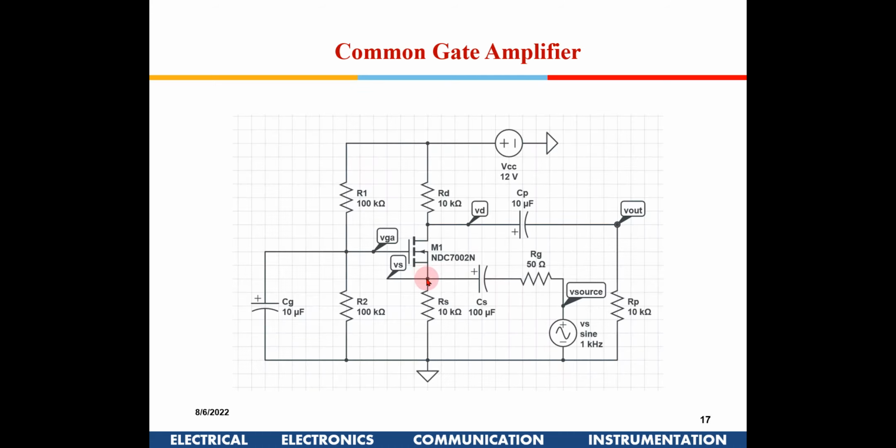Here, the signal is between the gate and the source voltage. Is there any voltage gain from this place to this place? There is no voltage gain. Voltage gain is between here and here. So the equivalent capacitance will come down. It will not get multiplied by the gain. Is it understood?